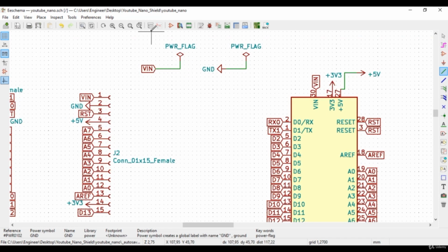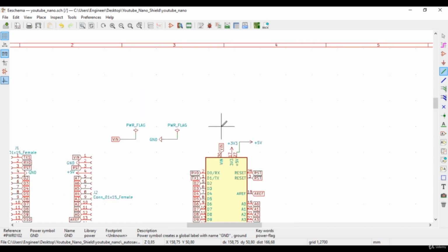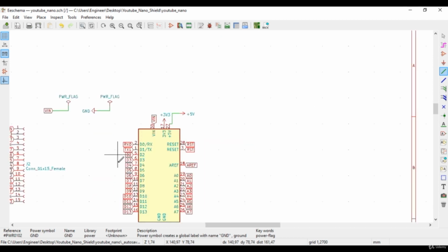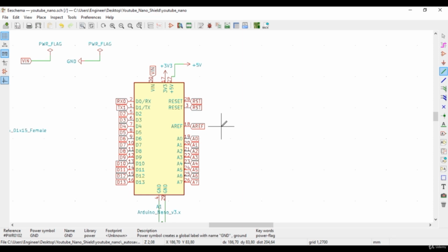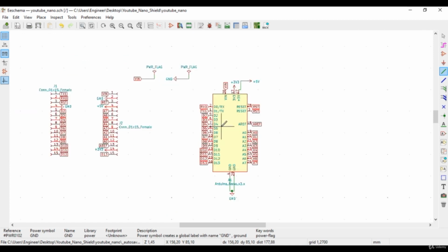Yes, friends, let's center our circuit here. Our circuit is finished. We need to assign a footprint on them, so we need to make PCB equivalents. It does not matter what the schematic shape we draw here is. Make it a triangle if you want. It does not matter. What matters is the footprint response. So we can call it a package equivalent. Do not worry if there are comments like, the image here does not look like Nano. This is the schematic part of the circuit. The important thing here is the pin assignments.